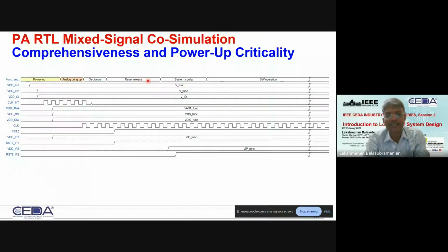And then the chip reset is released, followed by the system. Once the reset is released, the on-chip software can take over. You have seen there is a digital part and then on-chip power, and memories like non-volatile and volatile memories that are integrated. Now your instructions or programs, programmed onto the on-chip non-volatile memories, are loaded from external memories into the on-chip RAM, and then your system is getting configured and the actual functional application software starts running. This is how the whole system flow looks.